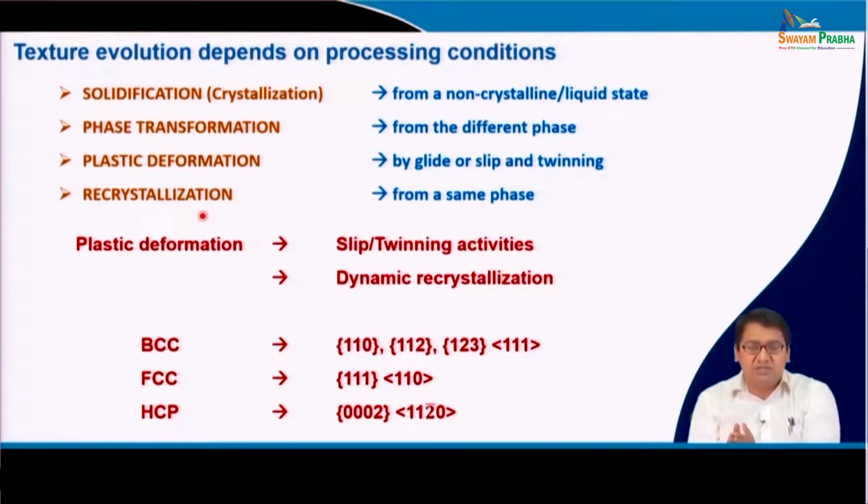It is held for some time, say 30 minutes or 1 hour, at about the recrystallization temperature, allowing it to recrystallize. So, during this process, the polycrystalline material will slowly reduce its stored energy by dissolving its dislocations, to do a recovery process. We will talk about this in much detail, but it will do a recovery process by formation of subgrain structure, or newly recrystallized grains will nucleate and then may grow a little bit, and then